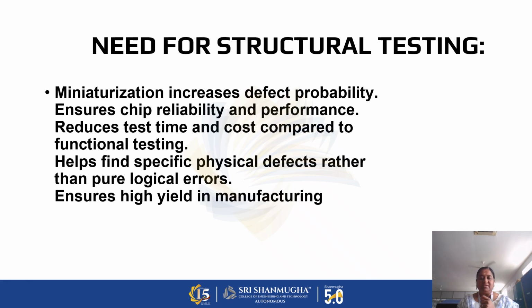When structural testing is performed, it reduces test time and cost compared to functional testing. It helps to find specific physical defects rather than pure logical errors. And moreover, when structural testing is done at various stages, it ensures high yield in the manufacturing process.